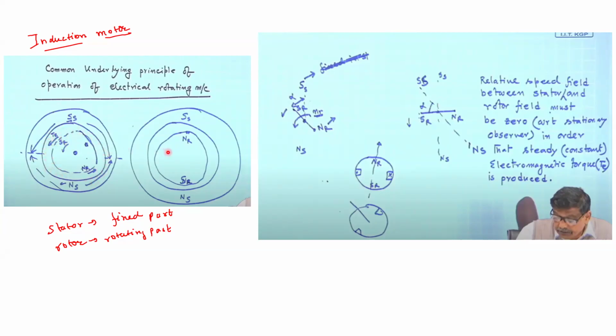So the machine will have some initial torque and it will rotate in this anti-clockwise direction. But after some point you may think, what will happen when the south pole of the rotor has reached the north pole of the stator, and the north pole of the rotor has reached the south pole of the stator? After this there should be no more motion.